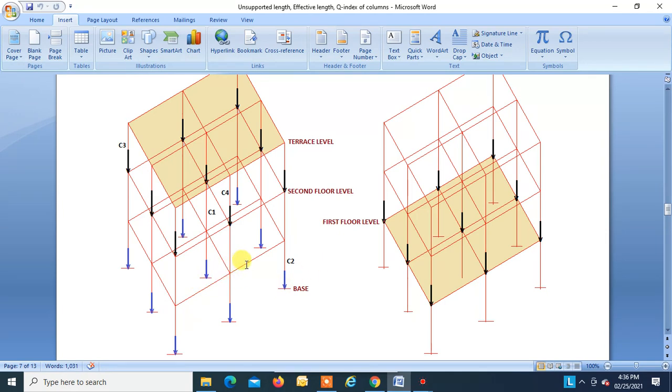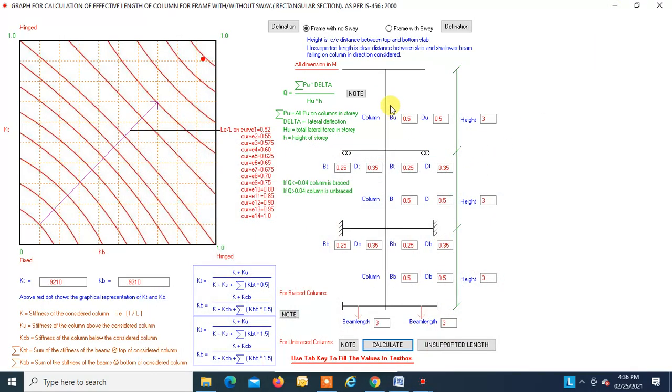There is no beam over here, and there is no beam at the bottom. Now we are again considering the y axis, only the y axis, right? There is only one beam falling at the top joint, and there are no other beams, right? And there is no bottom column, okay. So we'll change the input data similarly, okay. Now the size of this beam is 250 by 550, and the length of this beam is 5 meters, right? There is a top column, so this will remain, okay. There is a beam on this side, that is this beam,